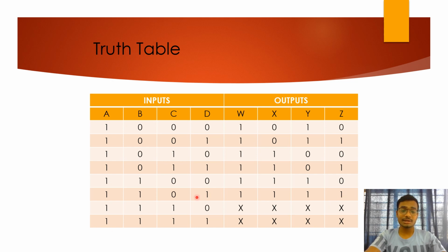So it's like this: 2 power 3 is 8, then 2 power 2 is 4, 8 plus 4 is 12, and 12 plus 1 is 13, right? So for the decimal value 13, after Excess-2, that is after adding decimal 2, I'll be getting decimal 15. That's the maximum limit I can push into a 4-bit number, right?